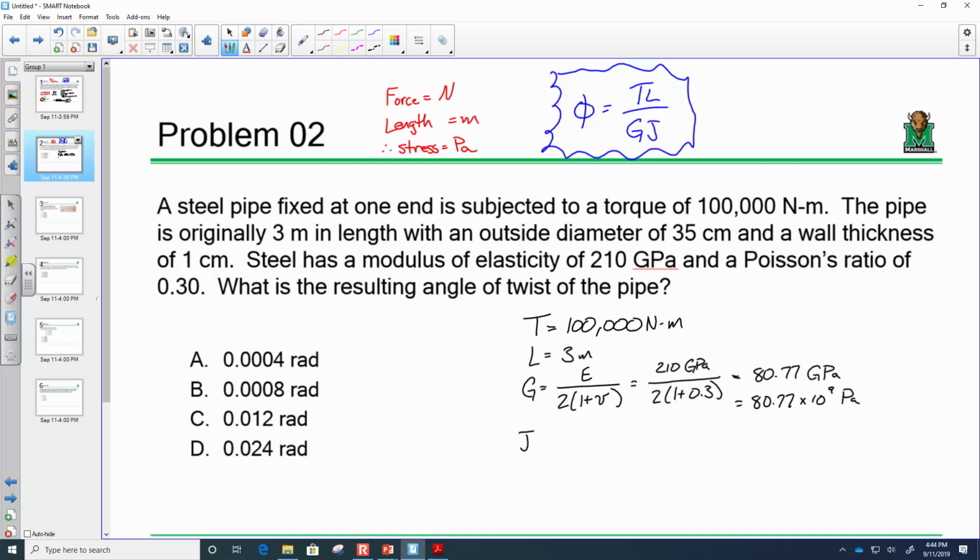But if you were to twist something that's non-circular, like let's say I have a shaft and I twist it, it actually goes in and out of the plane. So if I have something connected over here, it's actually going to butt into it. That's one reason. Another reason is that for anything being twisted, the most efficient shape possible is a circular cross-section. It's why if you look in automobiles or really any machine that's got something being twisted, it's circular in one way, shape, or form.